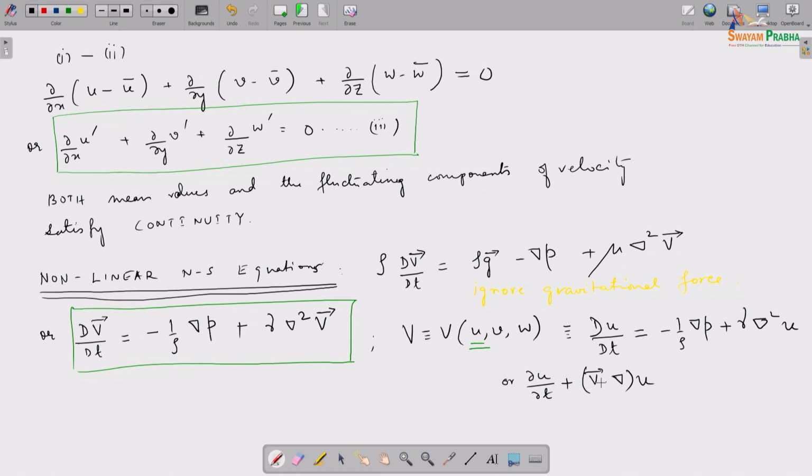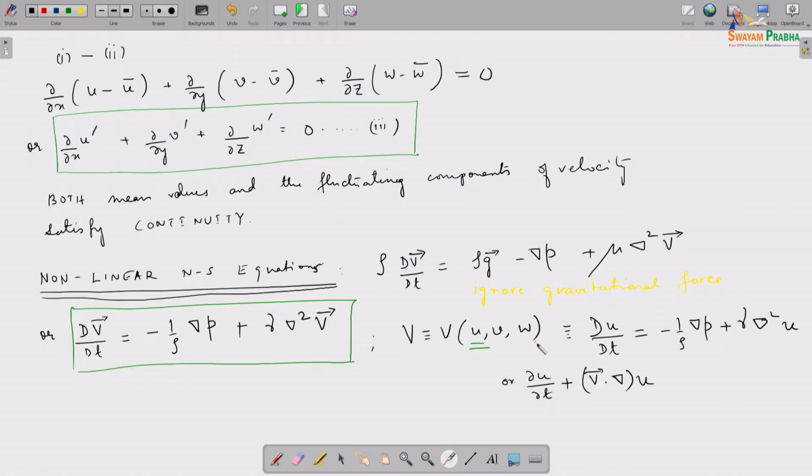Right. So, I am looking at the changes in the velocity. Whatever directions of velocity the fluid is moving in, in this particular case, it is important to note here that the fluid is moving in the x, y and z direction. Because of this total movement in the fluid flow in a 3D domain, what is the change in the velocity u component? The u component of velocity is the component of velocity in the x direction. The movement, however, is happening in x, y and z directions.